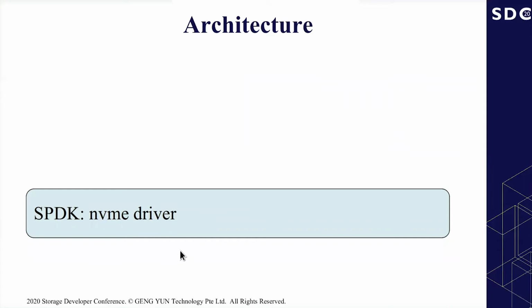However, SPDK is a software for data center production instead of SSD testing. So Pynvme added some features for testing and debugging. First, command log. Command log keeps all recent sent commands. There are 64-byte submission queue entries, and there are 16-byte completion queue entries, as well as the timestamps.